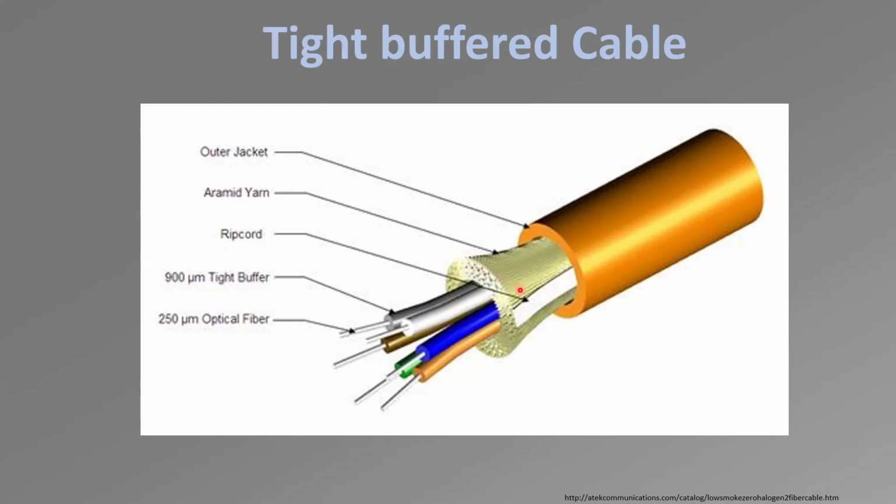What we need is extra protection from bumping around and maybe touching with some tools accidentally and things like that. Although, as much protection as this one has, still, when you run fiber optic lines, you treat them with extra care. If there's a wiring tray or cable tray, the fiber optic should be aside from all the other data wires, on the other side of the tray, just so it's not being bothered by anything else.